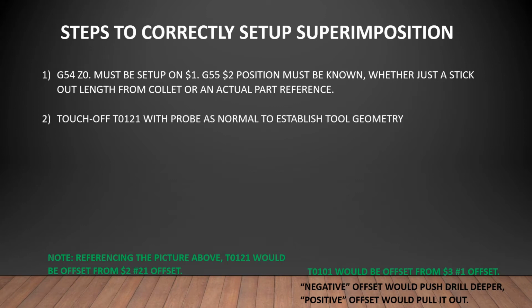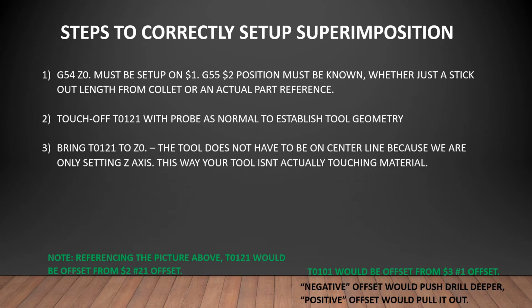Number 2, we take that tool and touch off that tool with a probe as normal to establish its tool geometry offset.